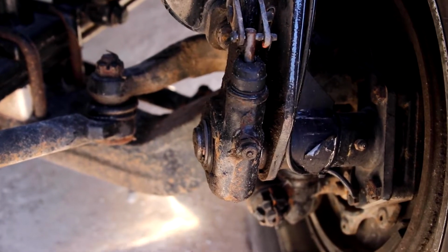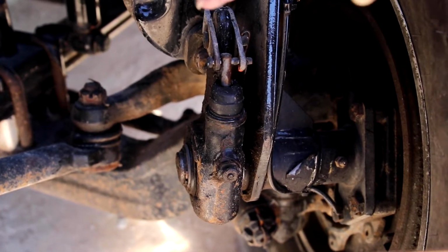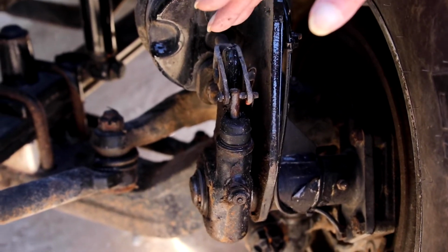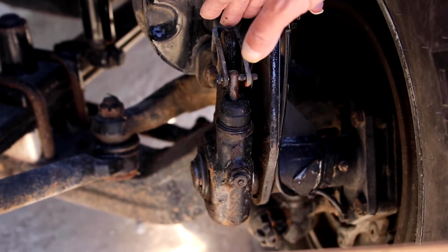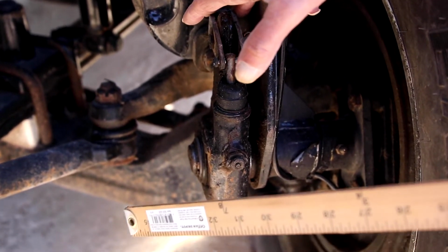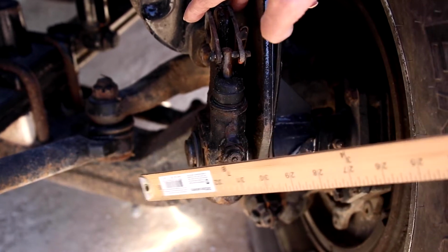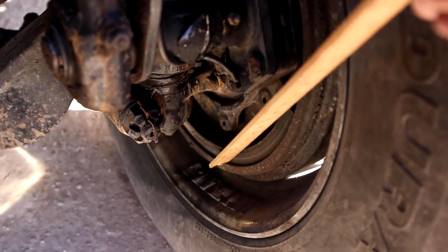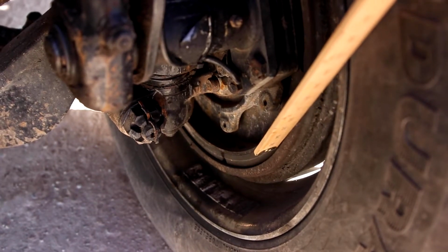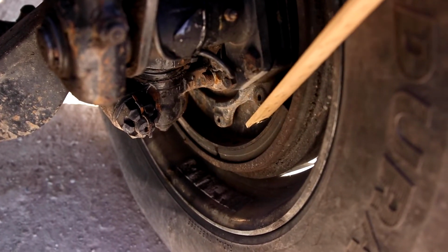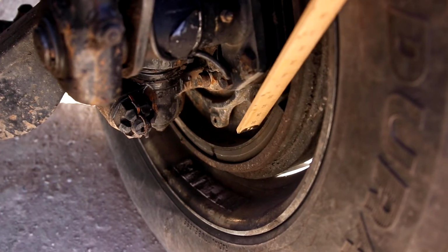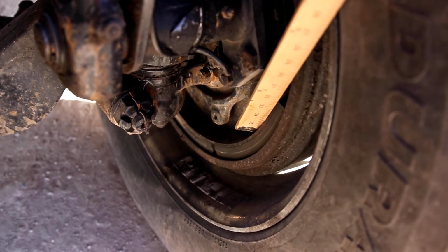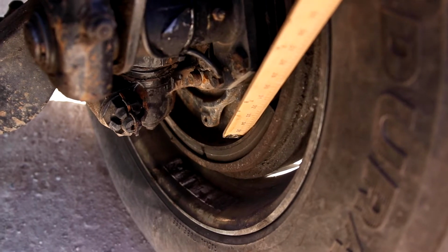What you want to do is say it's all mounted secure, not missing, damaged, or broken. And when the brakes are released, you should not be able to pull more than 1 inch on this slack adjuster. No more than 1 inch. Next, you have your brake shoes and linings right here. They're not missing, damaged, or broken. There is no oil or grease on them. No excessive wear. You must have a minimum of 1/4 inch of pad material on the brake shoes themselves.